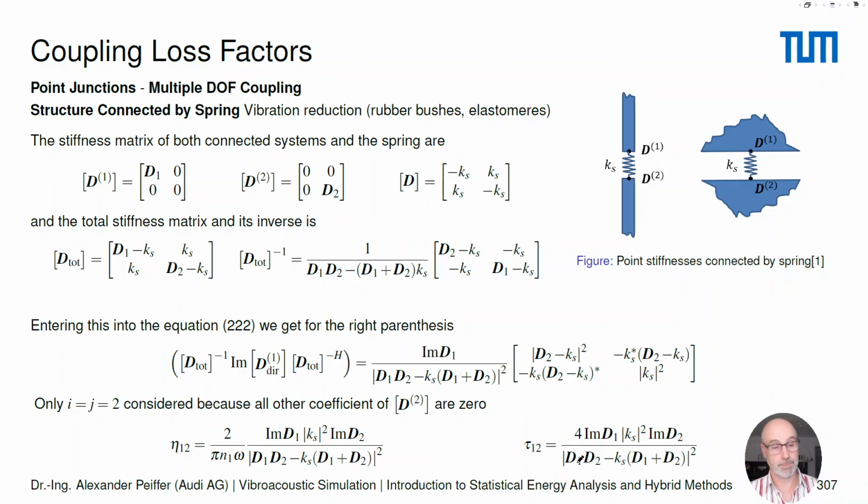So we could get back to scalars because we're just solving it. And we see that that's, again, a noise control feature. Now we know what is the nature of a spring, how soft does it have to be to create a reasonable isolation. Now, here it's the coupling, or the transmission factor, but the lower it is, the better is the isolation. So that means we have to use the low stiffness. The imaginary part of this stiffness must be low.